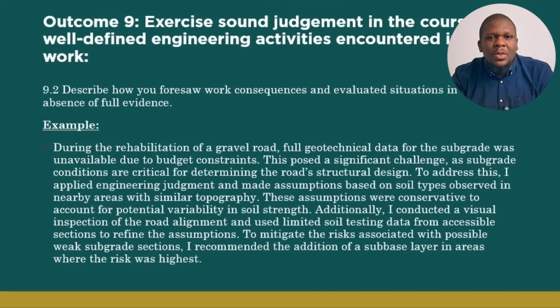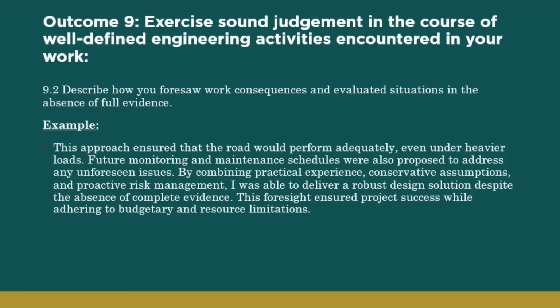Additionally, I conducted a visual inspection of the road alignment and used limited soil test data from accessible sections to refine my assumptions. To mitigate risk associated with potentially weak subgrade sections, I recommended the addition of a subbase layer in areas where the risk was the highest. This approach ensured that the road would perform adequately even under heavy loading.